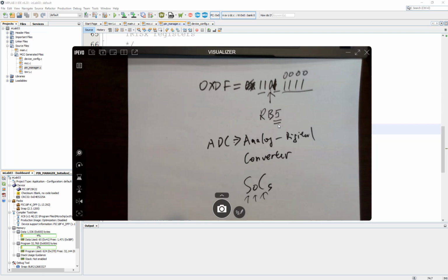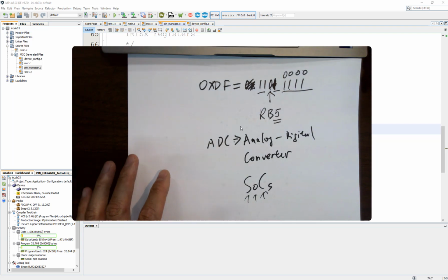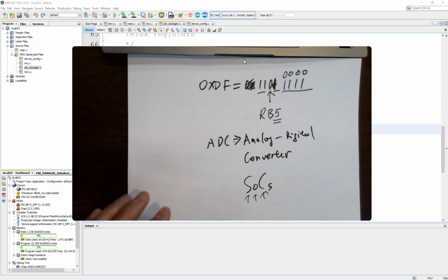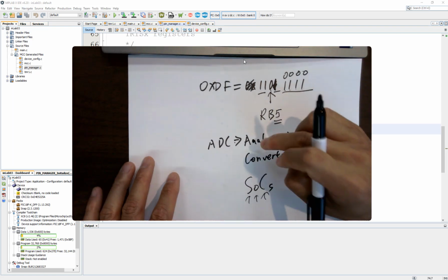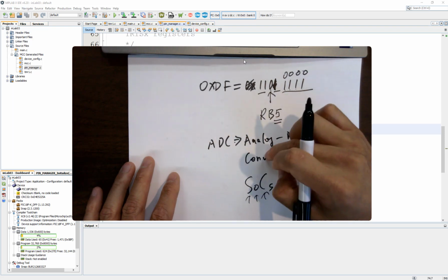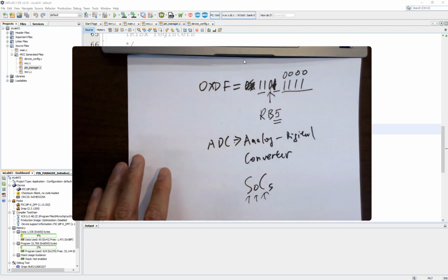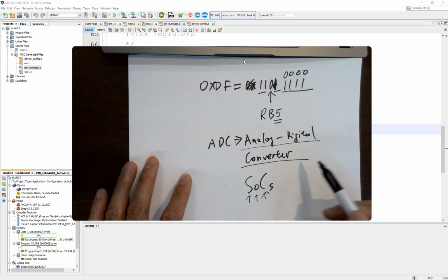So usually if you have analog circuits in there, you just basically cannot really easily use the 5 nanometer technologies, because you cannot design an analog system with those very short transistors. So usually these SoCs that have analog parts on them are somewhere around 65 nanometers or higher. So ADC is taking analog input and converting it to digital.